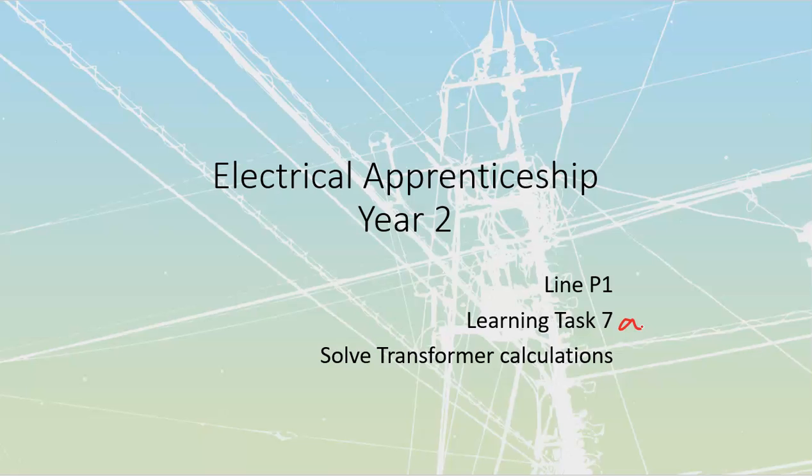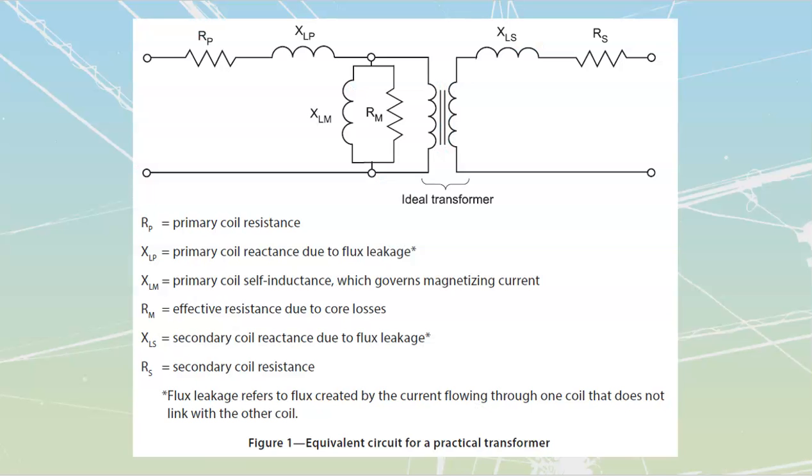So let's start with the very first drawing that they show us over here. This first drawing is a complicated drawing. I mean, it doesn't contain that many components, but it's the way that everything inside here is laid out. We're not used to seeing all of these series parallel RL circuits, right? You shouldn't see any capacitance inside here. There actually is some. They just didn't go too overboard, but there should be some parasitic capacitance inside here too. But they're just showing us a bunch of different types of resistances and inductances that all together are going to form the total of every transformer.